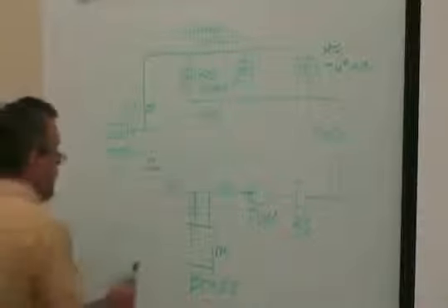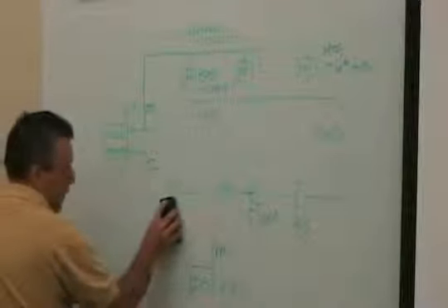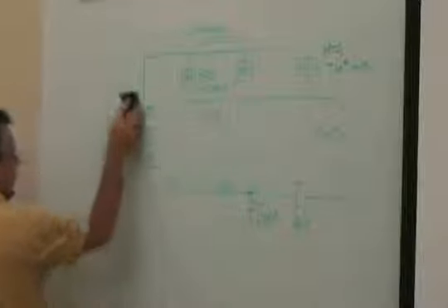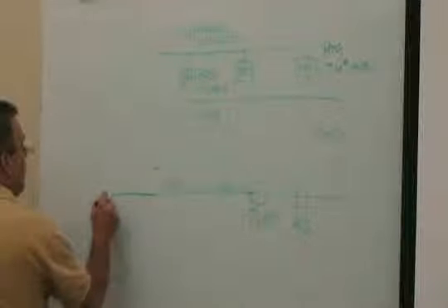Now, if I lose my boiler, I make this geothermal. In the geothermal system, you don't normally have a boiler. And this becomes a ground loop. I've got a question here. Say in the summertime, you got 100-degree water coming? I can have up to 100-degree water. Up to, okay. That's supposed to be hot, isn't it? Yeah, but what I can actually produce depends on what type of fluid cooler I'm using, or if I'm on a ground loop. If I'm on a ground loop, I may be up to 100 degrees.